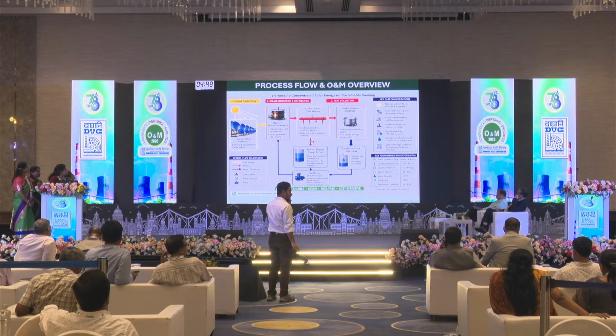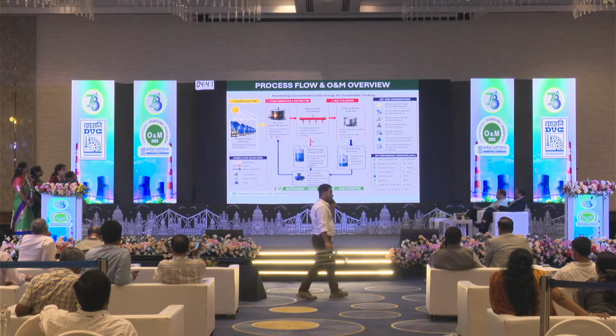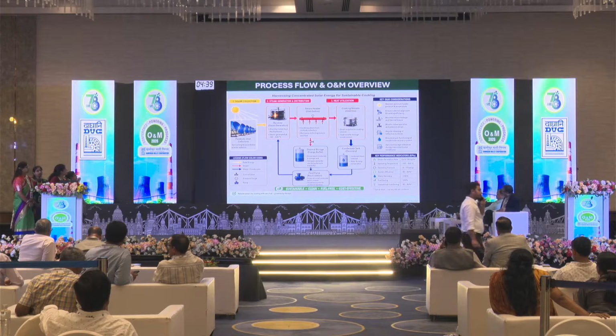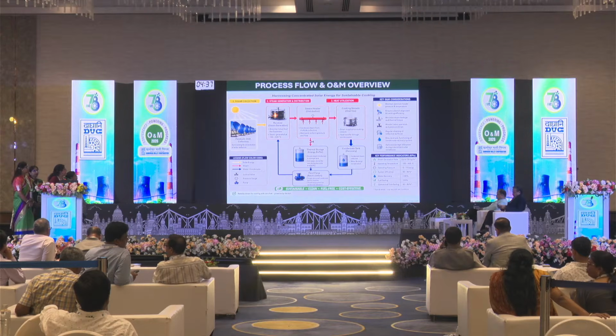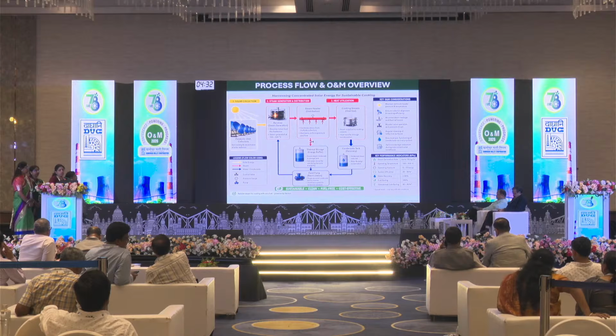Now let's understand the working principle behind this technology. It is pretty straightforward. As mentioned, the parabolic dish collector concentrates the solar radiation onto the receiving section, which then absorbs this concentrated heat, and then it transfers this heat to the feed water, which generates steam. It is collected into a steam header, which helps us in maintaining a uniform steam pressure, which is then distributed to different cooking vessels.